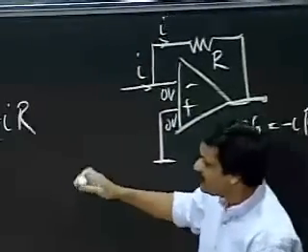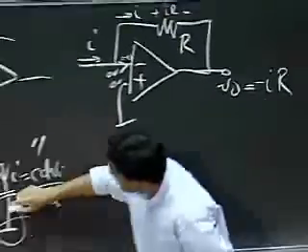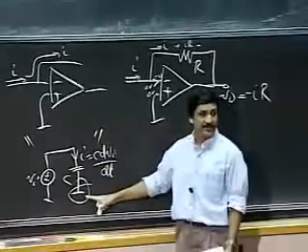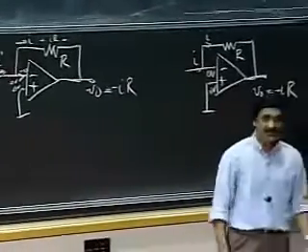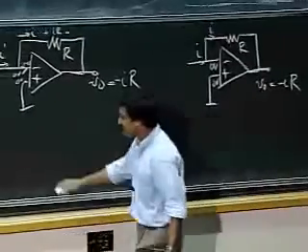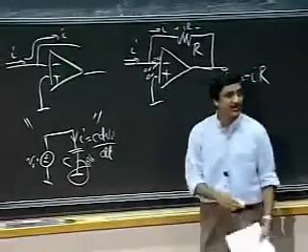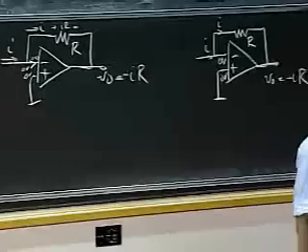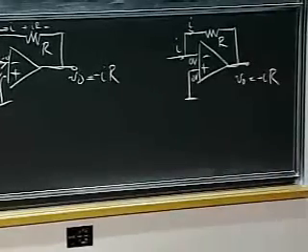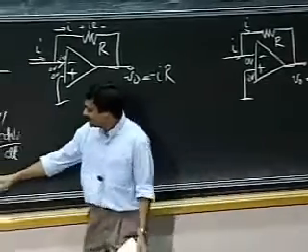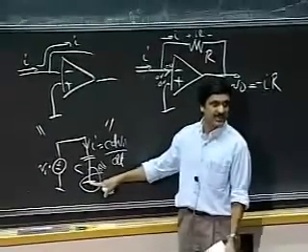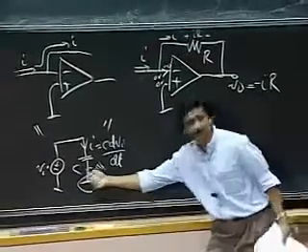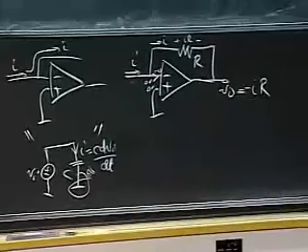Okay, so what I can do is, this is a ground node, correct? Now the poor little capacitor, what does it care whether it's a ground node or a virtual ground node? As long as it's a 0-volt node down here, what does it care? So what I'm going to do is stick this point, not here, but into a virtual ground node. I'm going to grab that point, take it here, and stick it here.